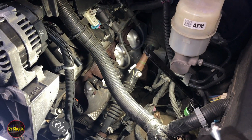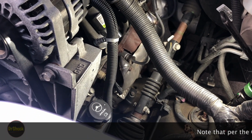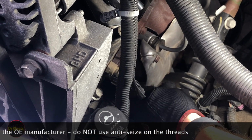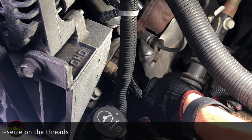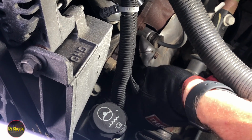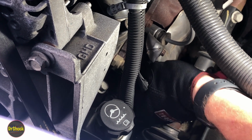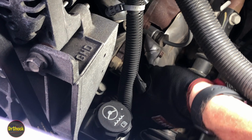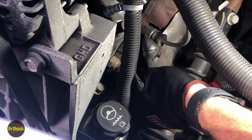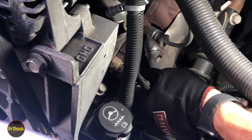I'm going to have to block your view for a moment, but we're going to put this guy in, and then we're going to torque him down to 11 foot-pounds. You always make sure you have clear eye shot of the threads, because you don't want to be groping around here and then mess up the gap. And these exhaust manifolds are super, super hot too. But I'm going to get this guy threaded by hand all the way, and then I'll come over here with a torque wrench.